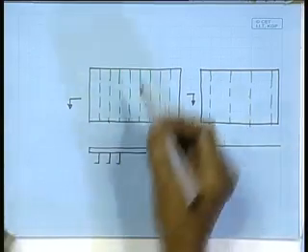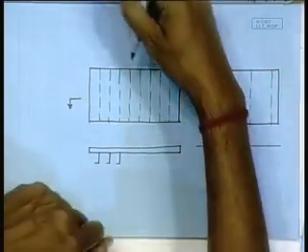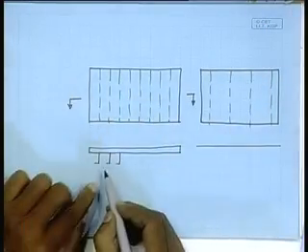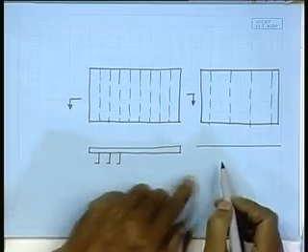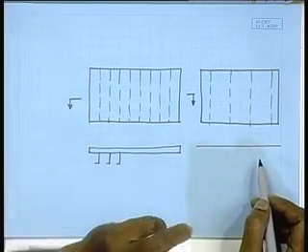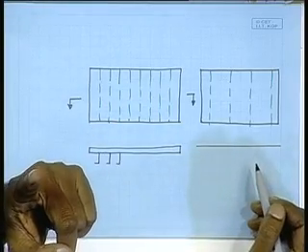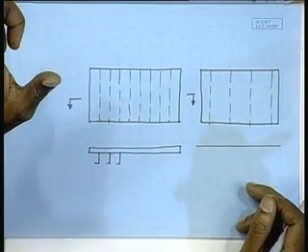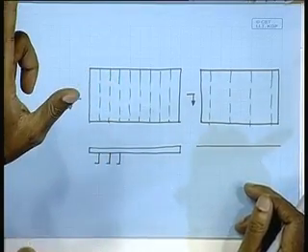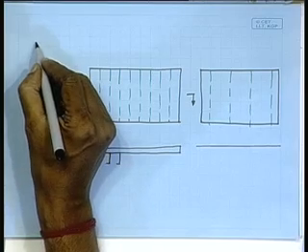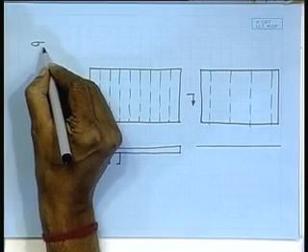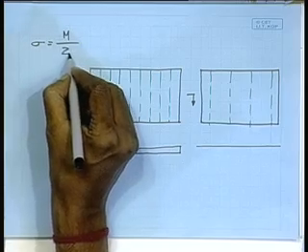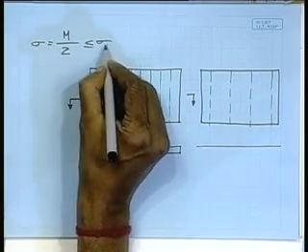Because here, whatever loading I am considering in this direction, the section modulus it is giving, because more number of longitudinals here, less number of longitudinals there, but the section modulus requirement has to be same, isn't it? Suppose both are being subjected to similar bending moment. Then what finally I have to satisfy is the stress whatever is coming, it should be less than or equal to your working stress.